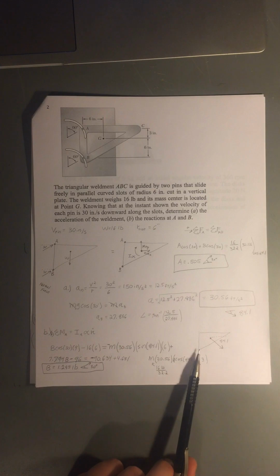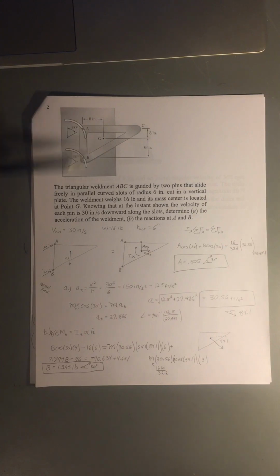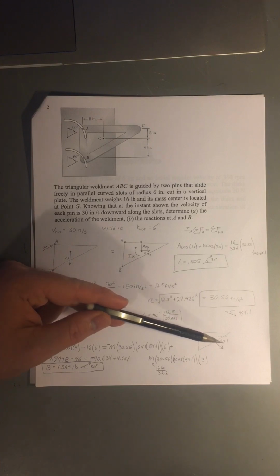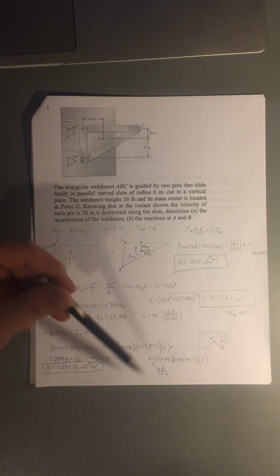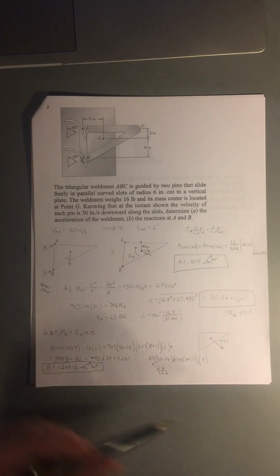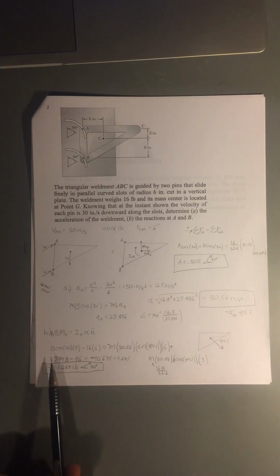And so we take the distance, which is 6 for the first one right here, and then multiply that by that component. So that would be sine of this angle, and then the other direction would be cosine of that angle. And then those are both multiplied by the mass, but we're given the weight, and so we have to divide that by 32.2, which is the acceleration of gravity. And then the vertical distance here is 3, so that's different as well. And then it's just a matter of plugging this into our calculator and rearranging it to solve for our reaction at B, which gives us a reaction at B of